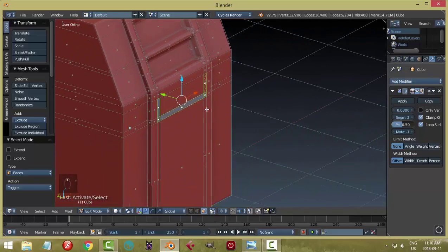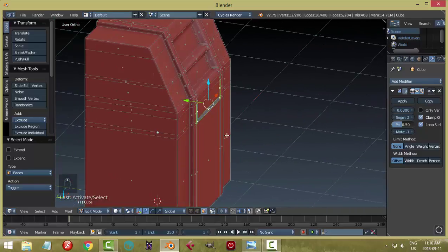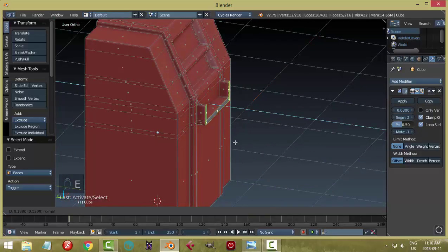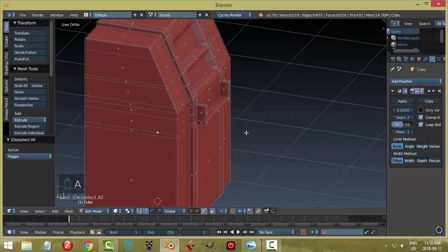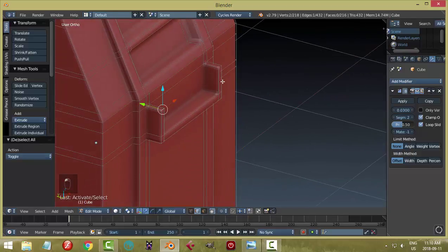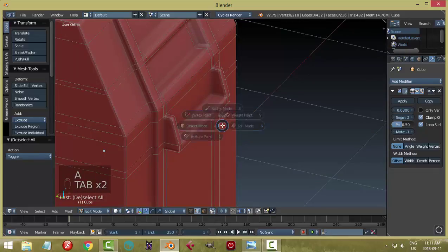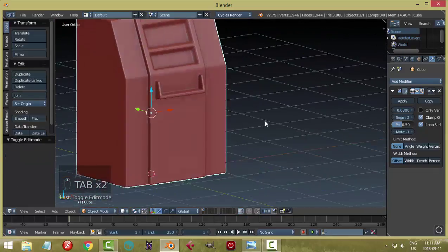I'm going to bring that out to create that little drawer area that the money comes out of. So I'm going to hit E to extrude, and I'm going to pull out just about that much. I'm going to go back into edge selection, select this top edge there and hold shift and get this one. And I'm going to pull back in the Y like that. Just like that. So I get a bit of an angle, so it's a little bit more interesting to look at, hopefully.